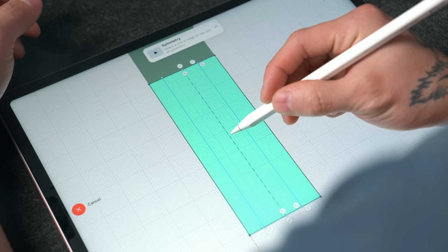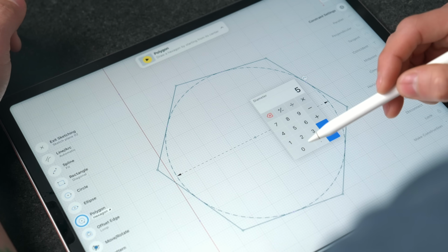geometry inside our sketch. And basically any shape can be turned into a reference geometry, not just lines. And these can be used as an axis for symmetry, defining size of odd shapes, for aligning sketching elements, or in our example, we're going to use this to set the position of our partitions.